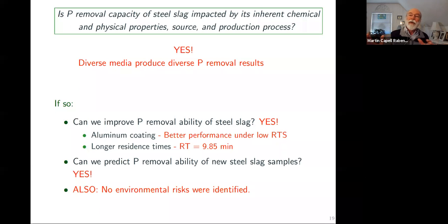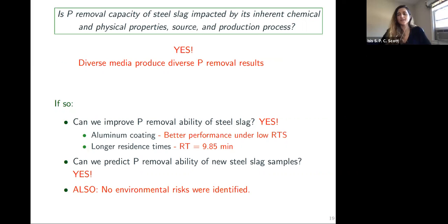Would you have to flush it and then capture all that solution and carry away these thousands of gallons of solution and find some way to dispose of that phosphorus that way? Yeah. So the way that we would proceed to do that, we took into consideration when we were establishing the number of pore volumes that we would use. So 5 pore volumes for a normal sized structure can be carried in those tanks that carry herbicides.